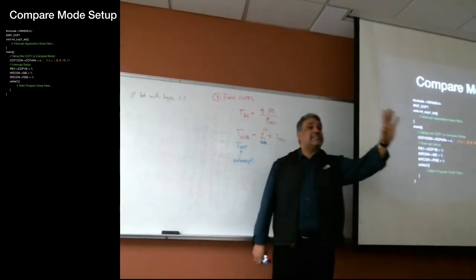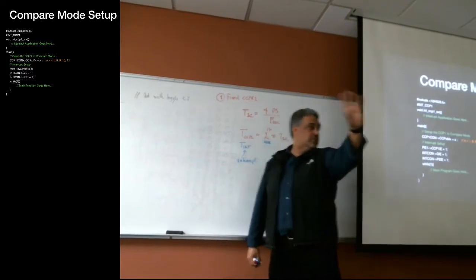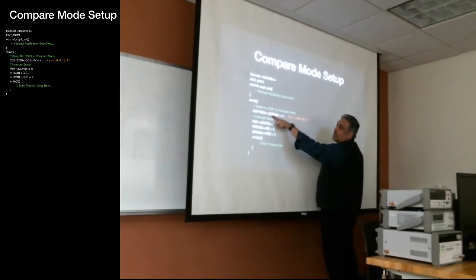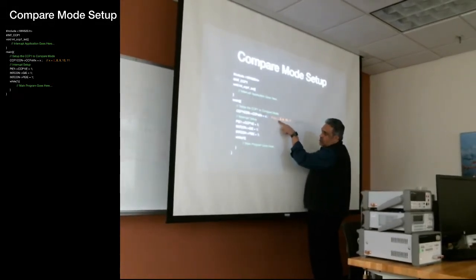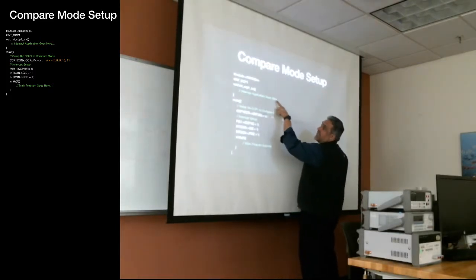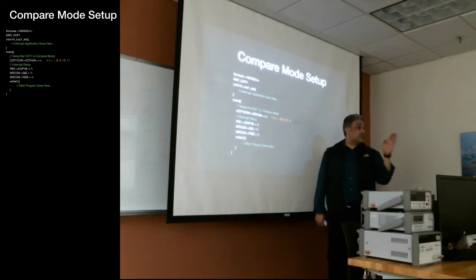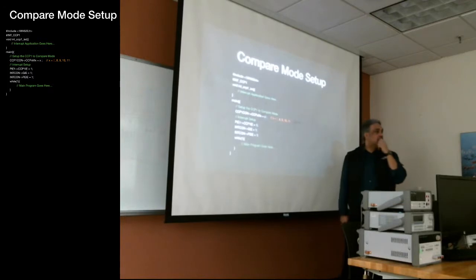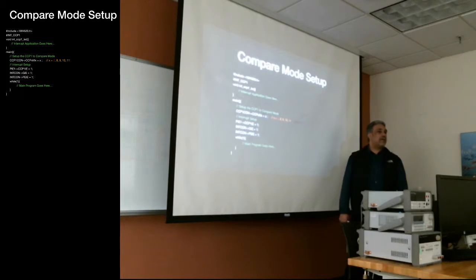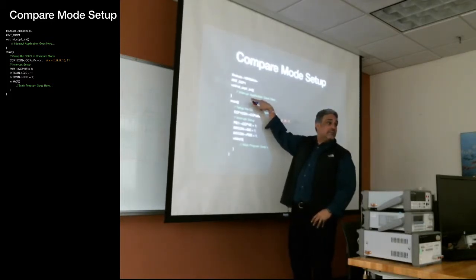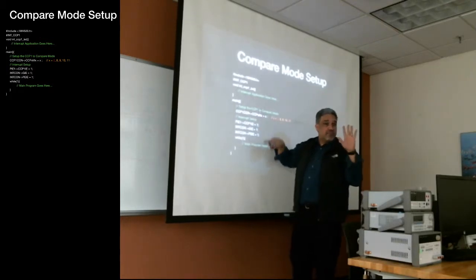Now, listen to what I'm going to say. Write this down somewhere in your notebook. Check this out. If you choose your compare mode with a 2 input, that means that even though there is nothing here in your interrupt application, pin C2 will toggle every time this interrupts, because it is a compare with a toggle. It will do it for you. You don't have to create a physical toggle in here. That's the important idea behind it.